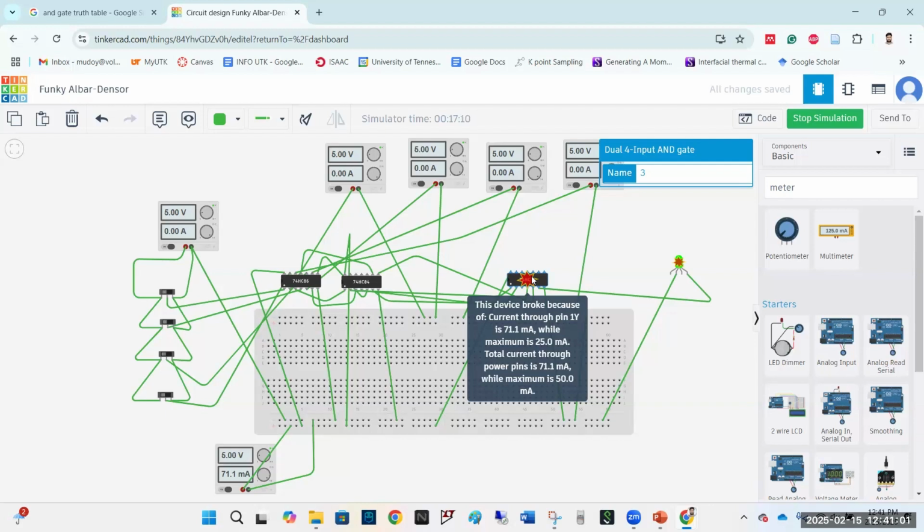By inserting this resistance, we are limiting the current. Because right now, without this resistance, the current level is so high that it is burning the LED and the ICs. So if we include a resistance like this in series with this LED, it may fix the issue. So let's do that.